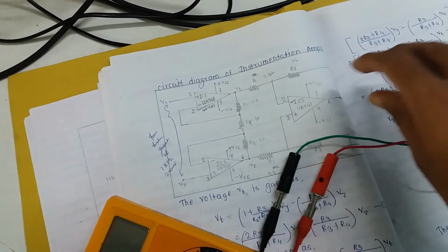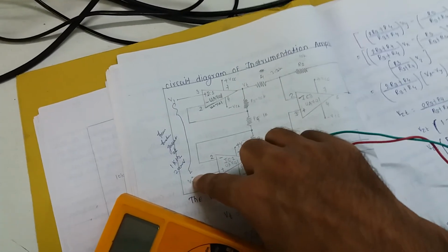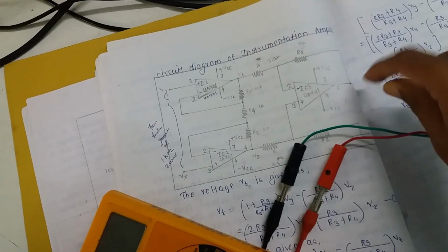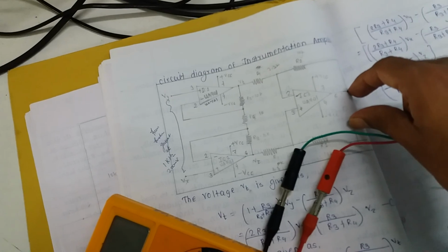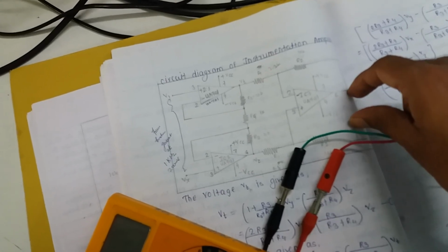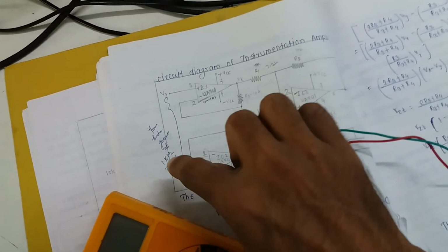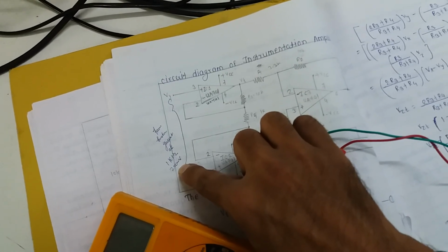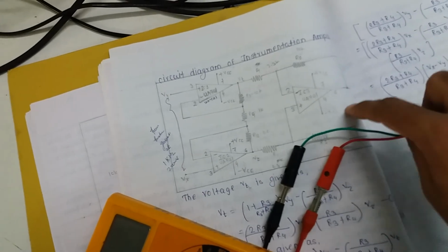We make the circuit as per the circuit diagram, and after that you connect the function generator plus terminal and minus terminal. Then here you see the CRO output across these two points. What is the peak to peak value? Practically I applied 500 millivolts, and it is increased to 19 volts.